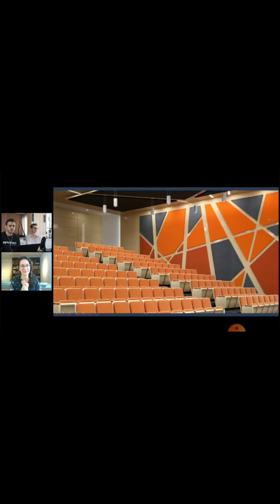Let's go on. And as we said, different materials, different purposes, and you can have them all in one room. The panels in the ceiling are reflective ones, so we are talking about an auditorium. They reflect the sound that comes from the stage to the people that are sitting. And the panels by the walls are the absorbent ones. So the sound will not come from everywhere at different times, because when it goes through different distances, it can go back at different times. Okay, we're going to talk about that shortly.